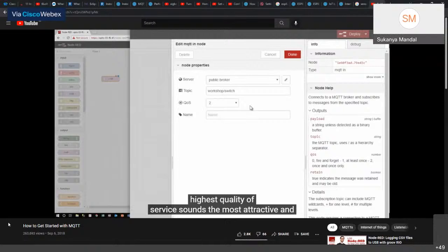The highest quality of service sounds the most attractive, and for control purposes, it is really the only option worth considering, but it does come at the cost of extra network traffic, since the broker and client must exchange confirmation packets, particularly for quality level 2, since both sides have to acknowledge the publication. Now, with my subscribed client all set up, I'll need to use this switch message to toggle a line.